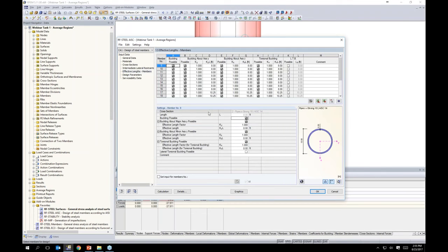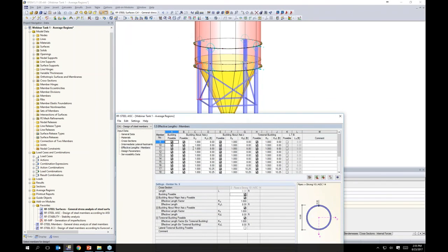The effective lengths is strong and weak axis buckling, torsional buckling, and for this, because we are designing per Chapter C, the direct analysis method from the AISC, we can leave our effective length factors equal to 1.0. The unbraced lengths will default to the full member length. So for example, this is why I created 2 column stacks here, so that the program will refer to the unbraced length as 8 feet as opposed to the full 16 feet, because I felt as though the strong and weak axis was braced okay with the addition of these horizontal beams.